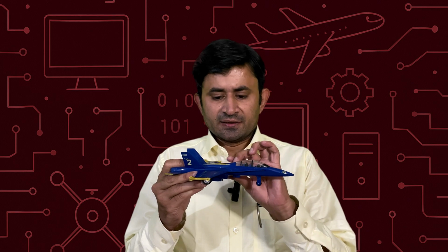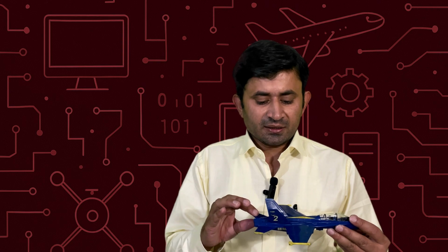So let's say we have an aircraft here. In MATLAB and Simulink, you can actually model the dynamics. For example, how the aerodynamic forces, propulsion forces, and gravitational forces are acting, using F equal to ma and M equal to I omega dot. So using force and moment, and also position and attitude, everything you can model and visualize in MATLAB and Simulink. But how to visualize the complete aircraft, that we can do in FlightGear.